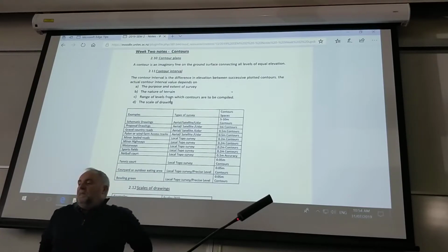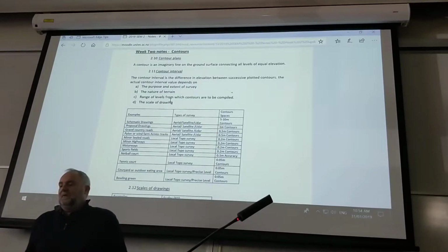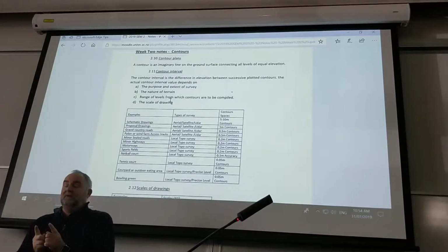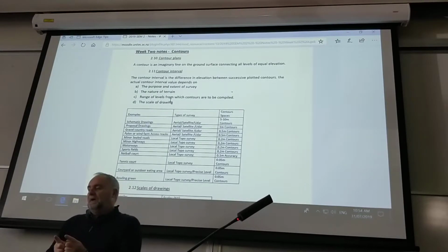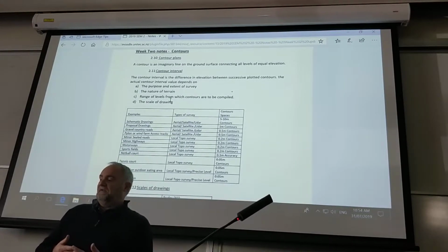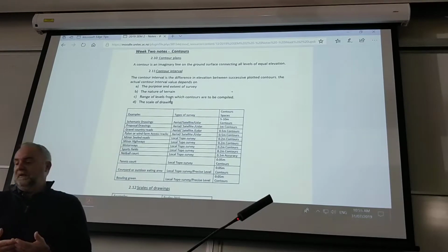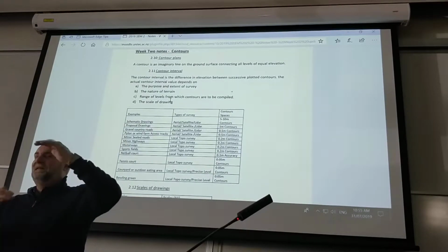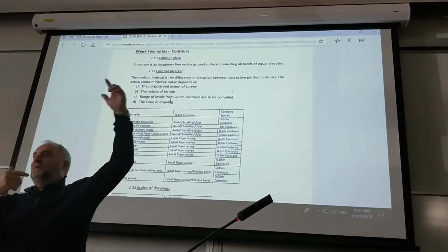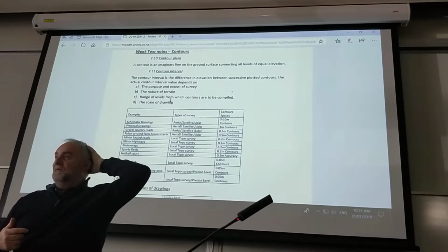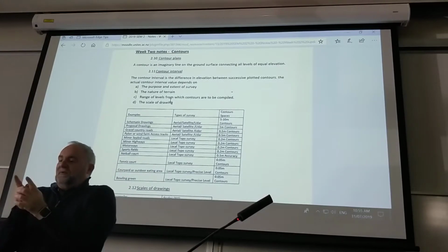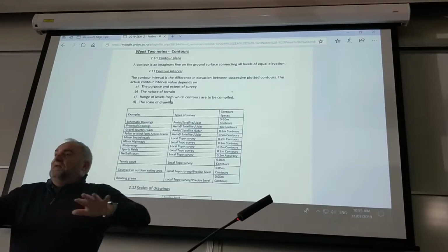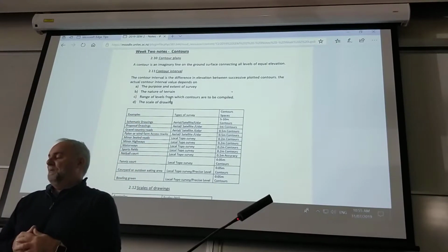So what I'm alluding to is that every type of plan you do will require different contour intervals to get the right result. So in my test I've said what would a typical interval for a tennis court be, and you can see to the side 0.05, 50 mils. And I've also set a schematic plan, for example, one of those ones you see on the news with all the colours saying the new motorway proposed from Warkworth to Wellsford or something. So it's over about 20, 30, 40 kilometres, and you don't really want contours down to this much. Every 20 metres is probably fine to show what the hills look like. So you could probably extend that to 5, 10, maybe 20 metre contour intervals.